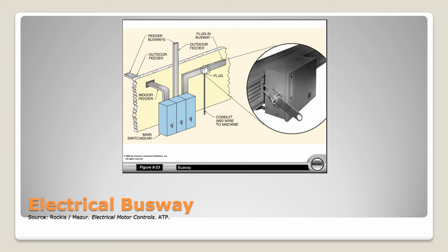Gas insulated bus typically just looks like a pipe, and the pipe is full of sulfur hexafluoride gas. Sulfur hexafluoride, sometimes called SF6, is a very good insulator. So you can have a very high voltage insulated by sulfur hexafluoride gas, and because it is such a good insulator, it allows you to have a much more compact bus, particularly when you're running high voltages above 138,000 volts.